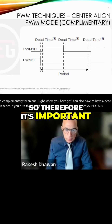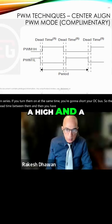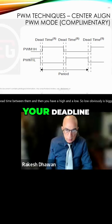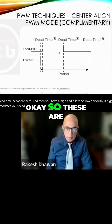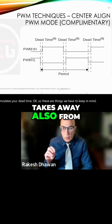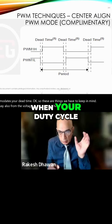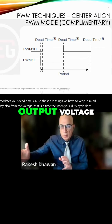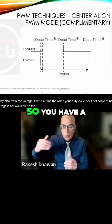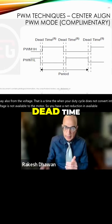So therefore, it's important that you have a dead time between them, and then you have a high and a low. So low obviously is bigger than your high because it accommodates your dead time. Okay, so these are things we have to keep in mind. Now, the dead time takes away also from the voltage. That is a time when your duty cycle does not convert into output voltage. That means that voltage is not available to the motor. So you have a net reduction in available voltage to the motor when you have a dead time.